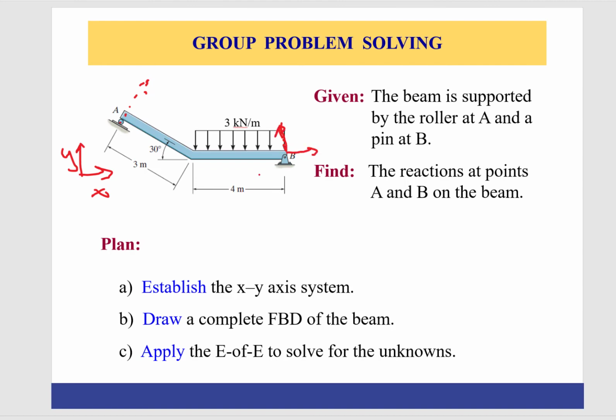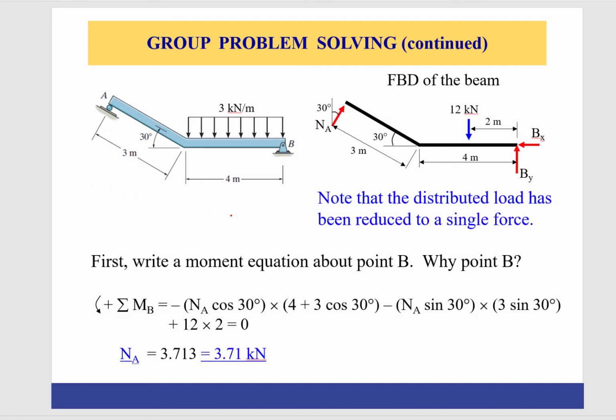Now, the question is how to calculate the reaction force in the easiest way. Before everything else, we chose Y and X as seen here. Let's actually scroll to the second slide. The reaction force is normal. We replaced the distributed load with a single equivalent force acting at the center of this rectangle. So it's 3 by 4, it's 12, and its location is the center, so it's 4/2.